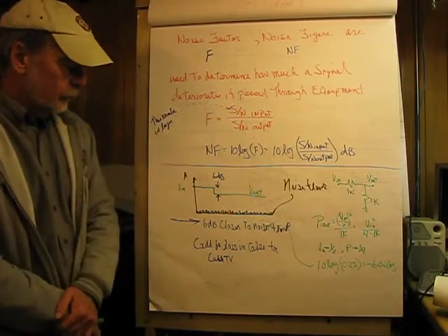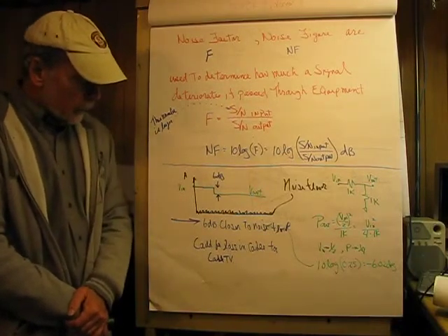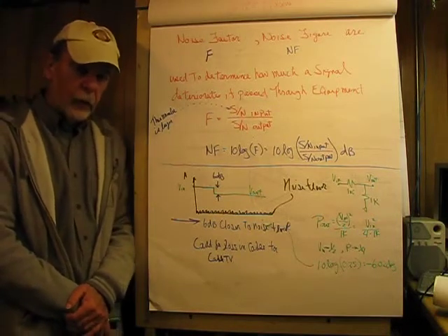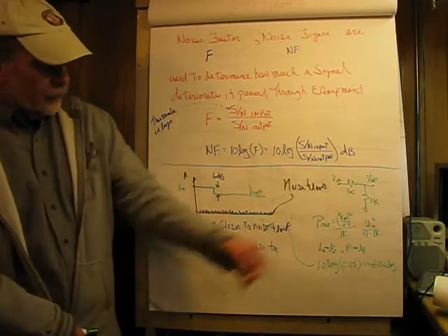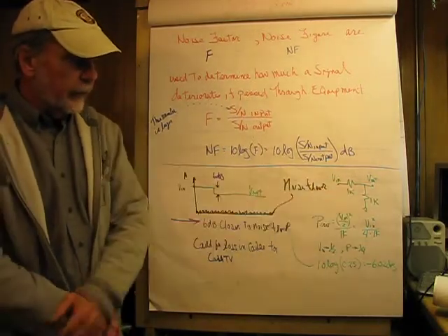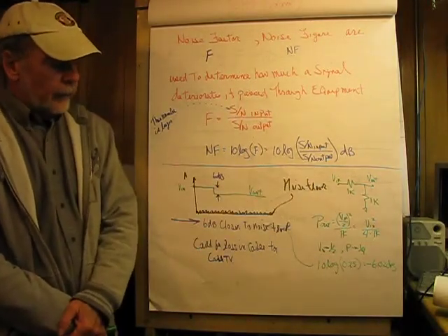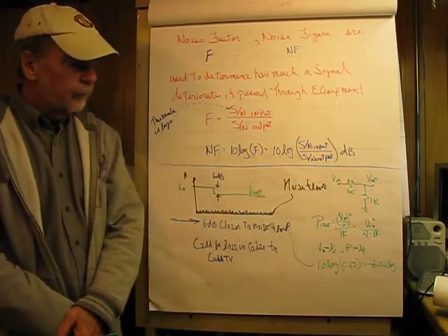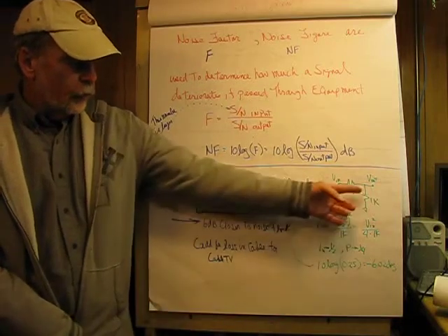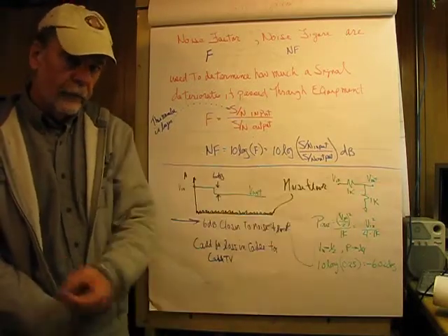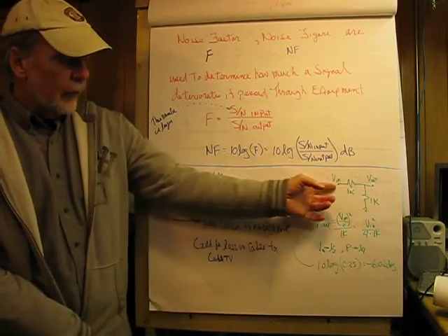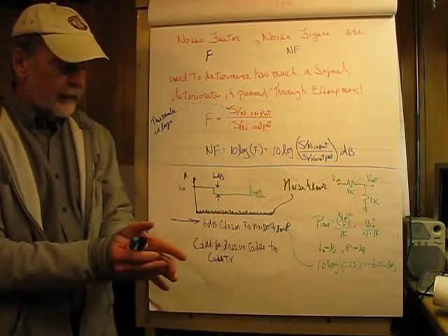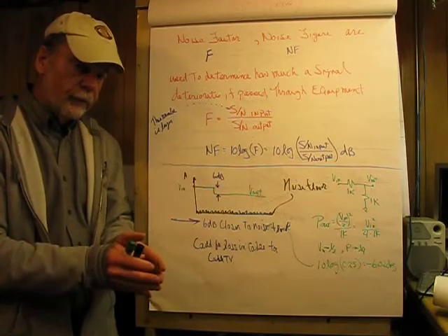Welcome to part 2. We're going to discuss signals and noise with regard to what it actually looks like in electronic equipment. Now, to model this, I just made up a voltage divider here of 1K over 1K, and if I were to find the power associated with Vn, it would be some number, and if I were to find the power associated with Vout, where the voltage is cut in half, the power would be 25%. So by cutting the voltage in half, the power drops to 1/4.